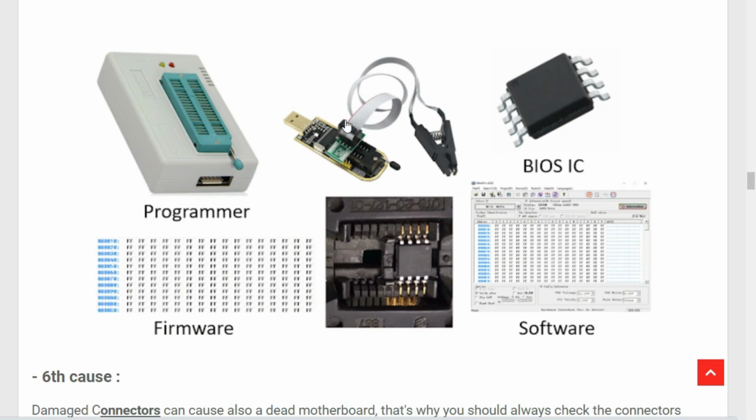This programmer, you can just connect it to the laptop via USB, as you can see, and then connect this support directly to the motherboard without desoldering the BIOS, and then you can program it directly from the motherboard.